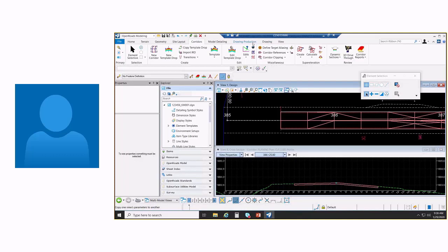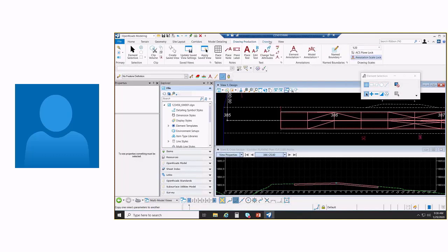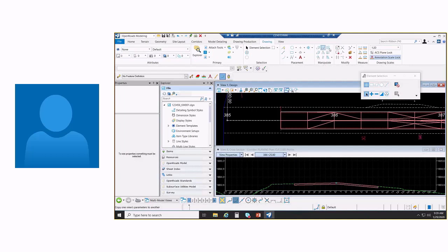So what I'm going to do is copy this element from my reference into the active file. So I'm just going to use a MicroStation copy command. And I'm just going to snap to that element, and copy it into this file. I think that was acting a little odd here, did it? Yeah. And I'll copy the next one. So I've got two elements in here, but again, they're just line strings. They're not really featureized, so they are duplicates.